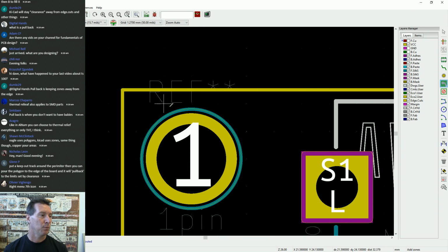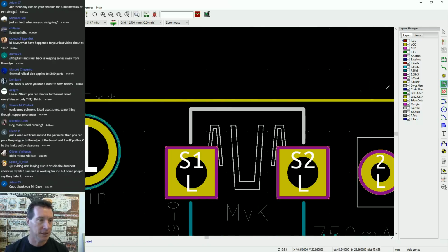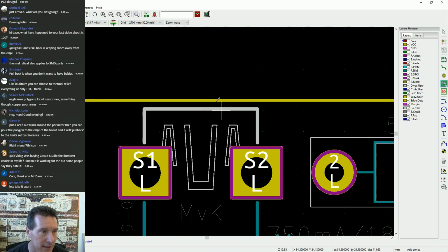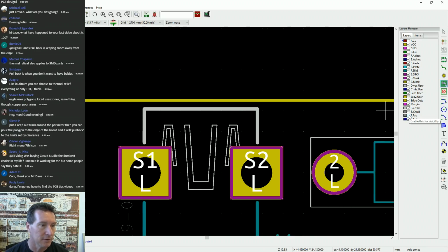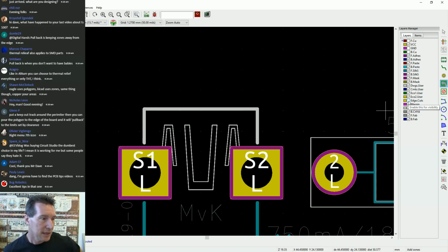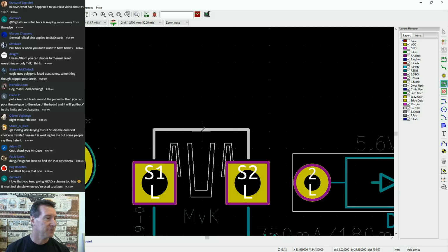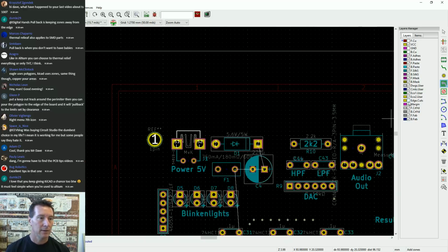Okay. When you've got a PCB, you've got the edge of your board here. The edge is defined on this particular layer. I don't know which layer they use in KiCAD. Fabrication layer, is it? No, it's not the fab layer. Bottom, no. Mask, pad, adhesive. Edge cuts, there we go. They've got an edge cuts layer, right? So your board is defined by...